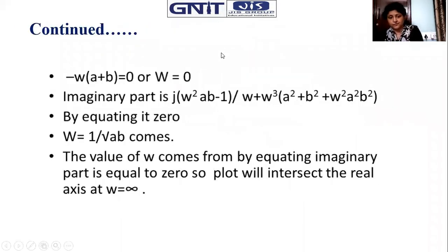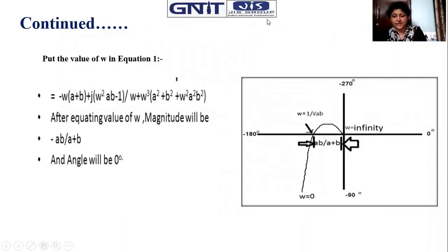Okay. So the diagram is that, see, you can simply draw the parallel line. The length is showing that it is infinite. So your phasor has the magnitude infinite at omega equals to 0. And what is the angle? It is parallel to the 90 degree line, that means it is at the angle minus 90. Now the phasor will move and cross minus 180, and it is merging to 0 because the final magnitude is 0.